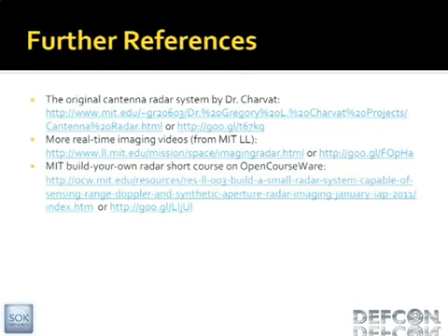So it wouldn't affect it too much, but that all depends on your chirp rate and your bandwidth and a bunch of other factors. You could make it have an impact or not. And the other thing is there's actually a way of disambiguating those, because you can chirp up and you can chirp back down. The Doppler shift is always going to change the frequency in one direction, but if you chirp the other direction, it'll shift it backwards. So all you have to do is figure out what's happening there and you can disambiguate them.